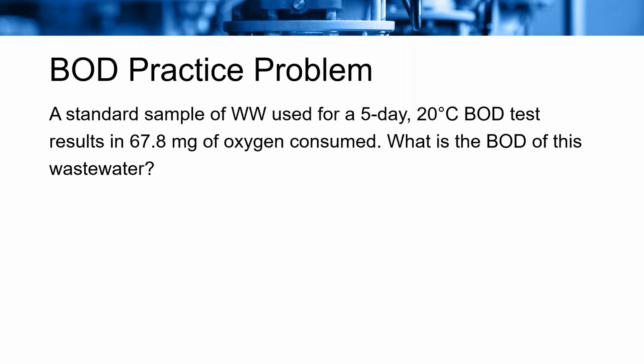Okay, so here's the practice problem. It's the same thing, a standard sample, 300 milliliters of wastewater is used for a 5-day, 20 degrees Celsius BOD test, and it results in 67.8 milligrams of oxygen consumed. And the question is just like the last one, what is the BOD of this wastewater? So we'll give you guys about a minute to solve this, and then we'll put up the poll question.